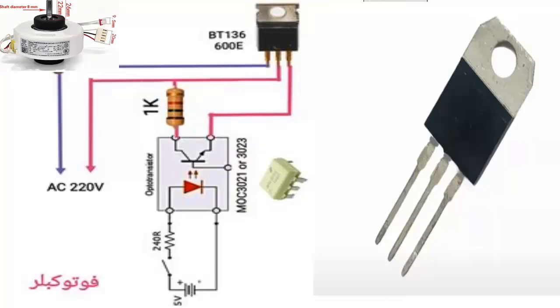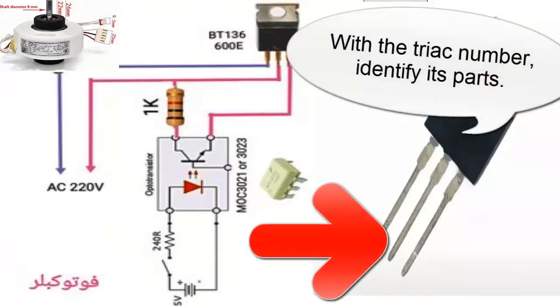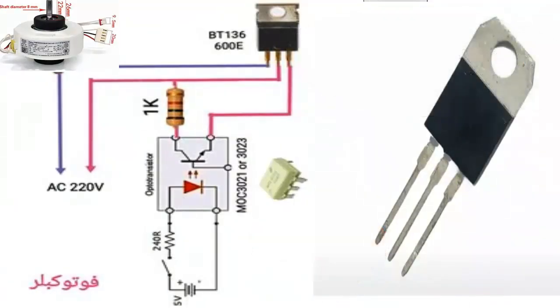C. Locate the Triac, and become familiar with its pins. Generally, the pins are labeled as MT1, MT2, and gate. Use the serial number to identify them. D. Disconnect the fan and the power supply from the electronic board. Set the multimeter to electrical resistance mode.